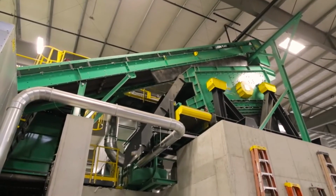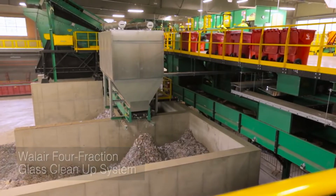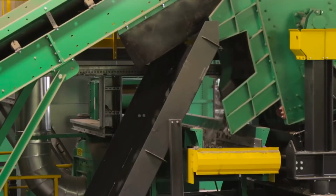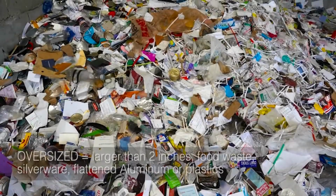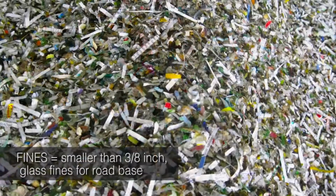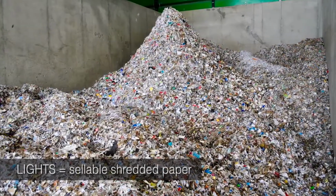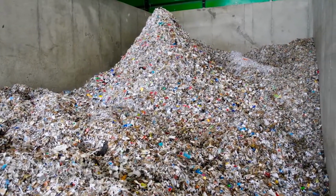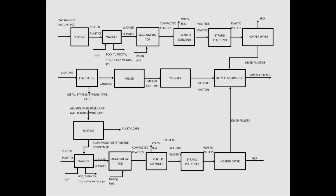The first one is the compatibilization of polyethylene terephthalate, polyethylene, and polypropylene. The second one is the presence of inks in case of printed laminates, which may affect properties of recycled compounds. The third one is the presence of aluminum in case of metallized laminates. The fourth one is the presence of various adhesives for binding different layers in laminates. And lastly, difficulty in handling of laminates.